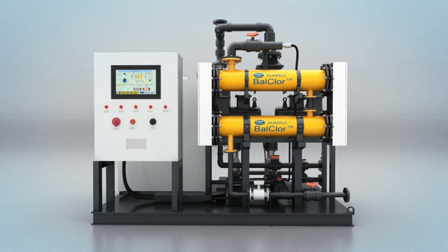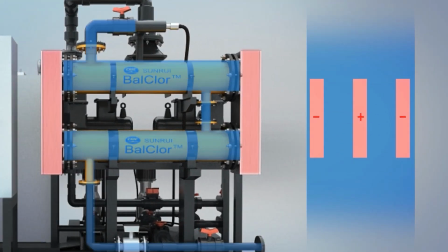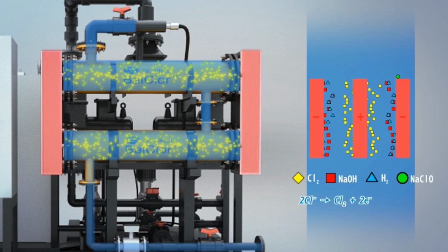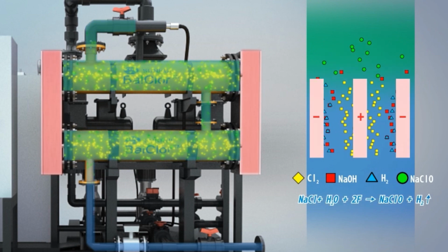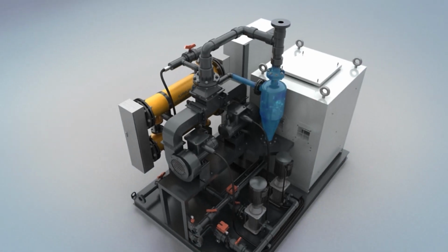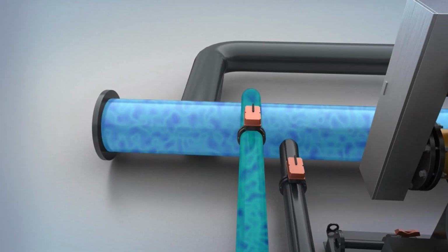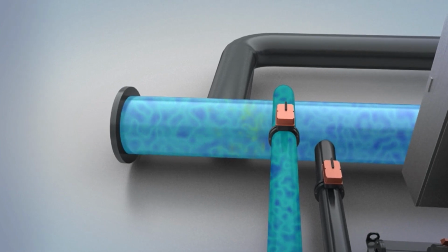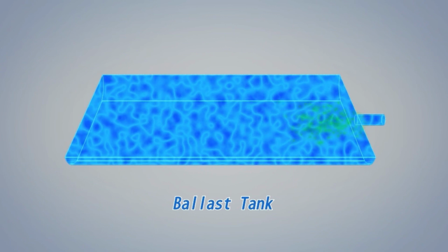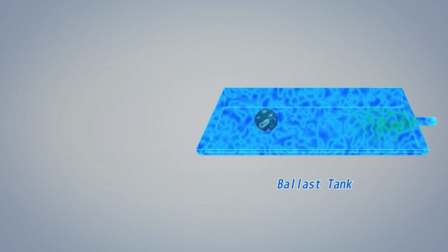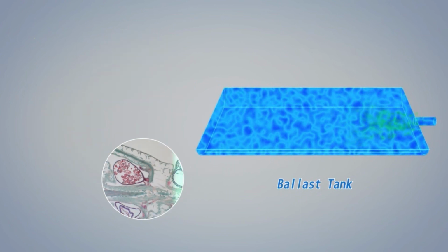During the electrolyzing process, chlorine is created from electrolyzing seawater on the surface of anodes, which will be dissolved in water rapidly, forming high concentrated sodium hypochlorite solution, and will be injected back into the main ballast water pipe after degassing hydrogen during the reaction. Sodium hypochlorite is an effective disinfectant solution, which can sufficiently kill spores, larvae, and pathogens to meet the D2 regulation requirement.